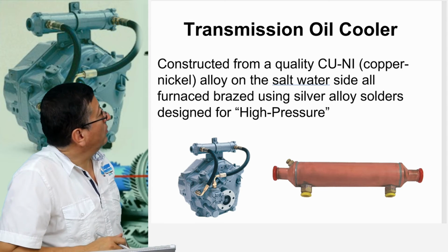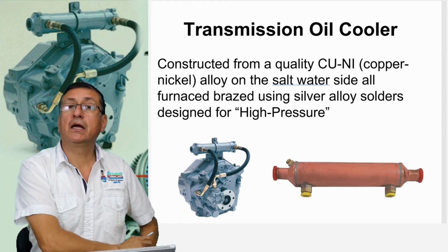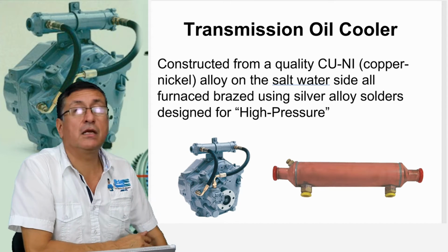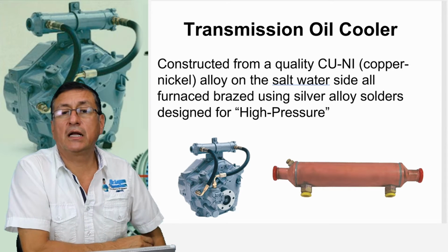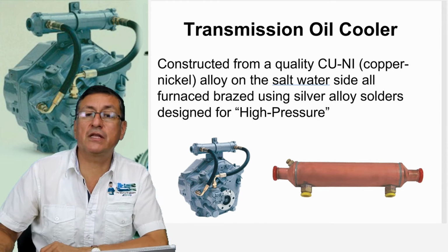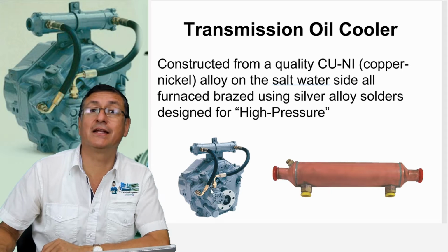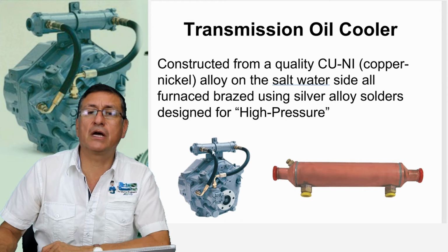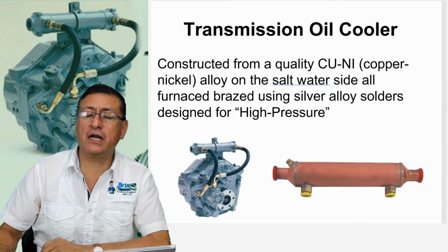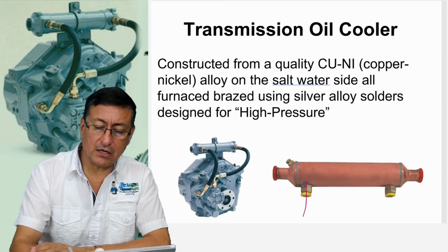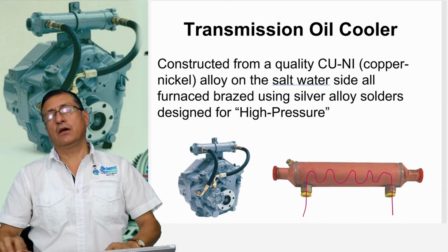This is the oil cooler in a typical inboard transmission. This is an inboard diesel transmission, and yes, this is the oil pump. We are going to analyze the oil pump in the next episode. Those are the lines. This is the oil cooler. The salt water enters over there, continues, enters here, continues over there, and the oil enters here, circulates over there, and returns. That's the oil cooler.